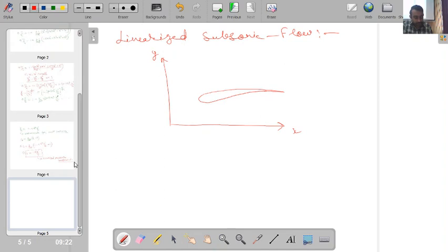Okay. So the profile of the aerofoil can be given as, say, y is equal to a function of x. Okay. So the surface of the profile is given by y equal to function of x. Okay, so for each x, if I know this function I can find out the profile. Now say I am at this point, the streamline which will be passing through this will have a velocity direction something like this.